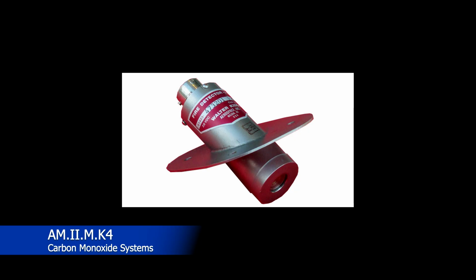Anyhow, the way that these work, they're designed to alarm whenever they detect the presence of a prominent specific radiation emission from a hydrocarbon flame. In other words, whenever something catches on fire. There's two types, IR and UV, based on specific emission wavelengths they're designed to detect. So basically, if they are looking for fire from a certain type of system, they're going to use IR. If it's a different type of system, maybe they use UV, based on what those systems are made out of or what they're burning.